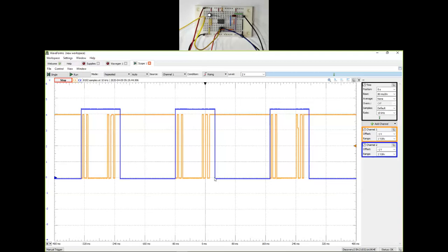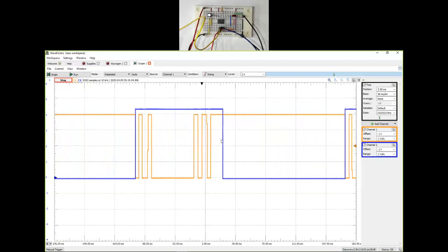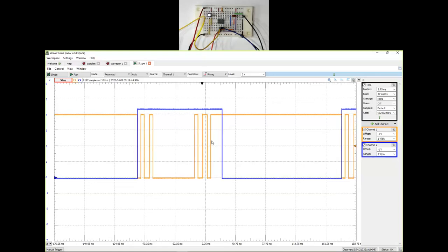But ideally, you would want to make it tighter so you can in fact come back lower. So if I zoom in here to indicate what I mean, this blue line right now is happening a little bit after all that bounce has finished. So if I were to bring it tighter to where the bounce is, I can do two things. One is reduce my energy consumption because it's on for less amount of time. But the problem with that is that I will be running very close to where the bounce is. So I might accidentally not be able to do that debouncing efficiently. So there's a risk versus reward scenario there.